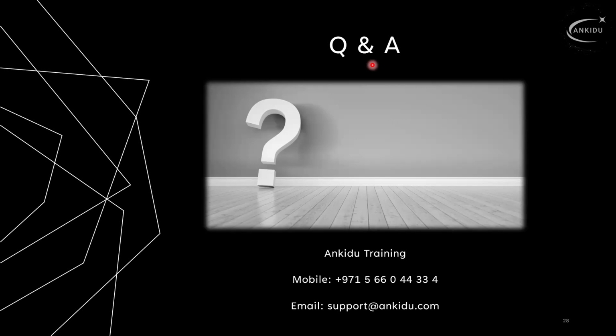The well is seized. Go back in your mind to the illustration where you have the tubing and annulus in a stable condition. Let's say we didn't open the well to the surface till now, so there is accumulated gas inside the annulus and tubing. We need a small diameter to flow because velocity plays a crucial role in unloading the well. We can benefit from this gas accumulated inside the annulus to help push up the liquid from the tubing, because we close the annulus and open just the tubing, and then we have enough velocity to flow the well to the surface. That's why I'm saying the annulus pressure can help.